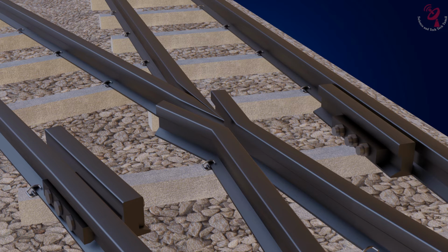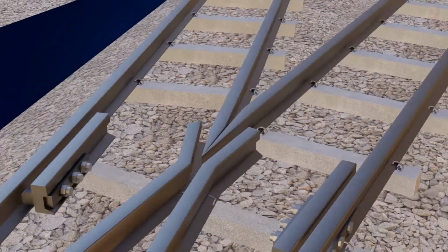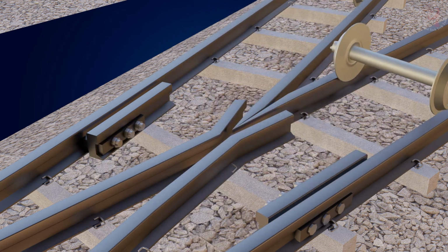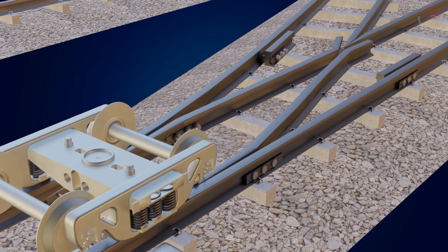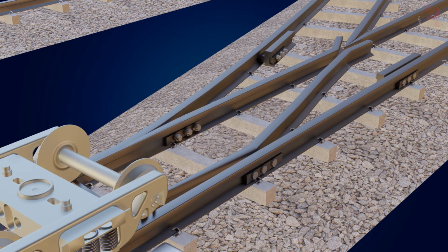Another issue in this track changing mechanism, the train wheels may travel another path of crossing nose. To overcome this issue, additional rails are fitted at opposite rails to the crossing nose. This is called a check rail. These additional rails will prevent the wheels traveling in the wrong direction. For example, if the wheel crossing the crossing nose tries to deviate from the track, the wheel on the opposite side will prevent it. Thus, a train can easily cross this crossing nose.